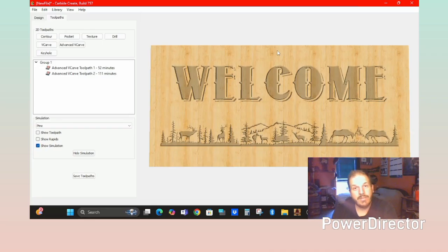So, now that we've got it for this one, and see, both of these would be saved as a single toolpath, and we would be able to cut this all at one time on the Shapeoko, because it will prompt for a bit change, it will reset its Z-axis, all of that. The Ultimate B, unfortunately, is not set up yet, so we're going to have to redo this if we decided to do this on it.